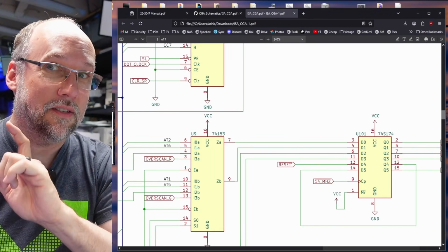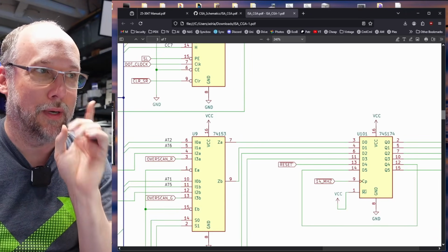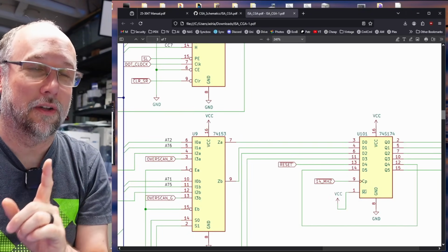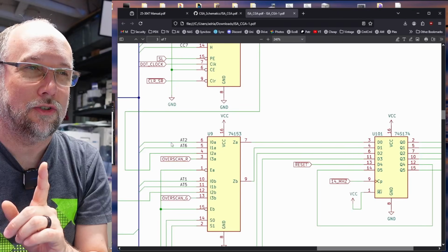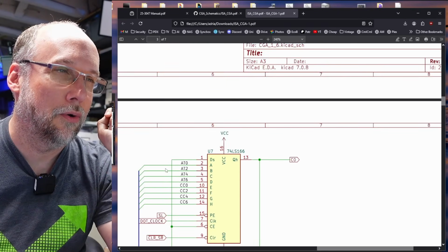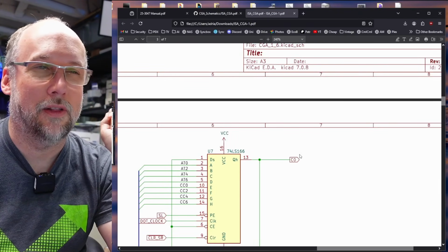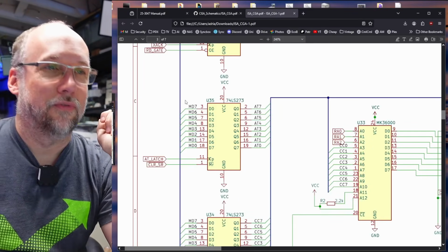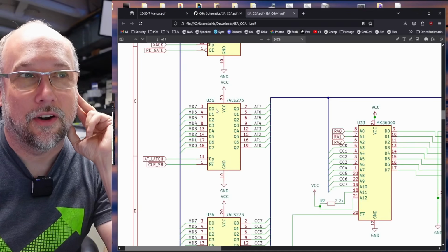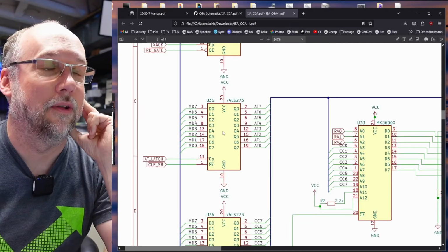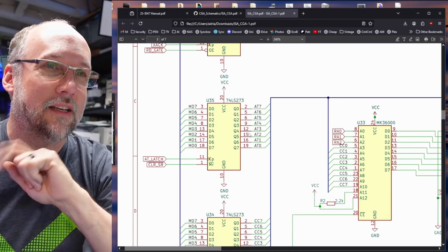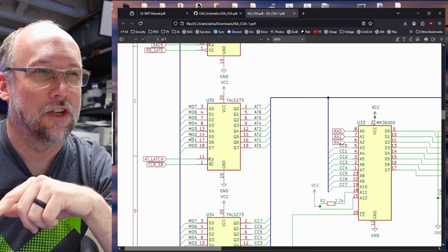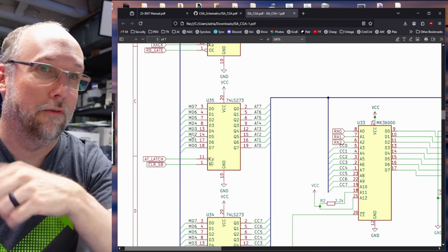And that right there tells us that if we were dealing with this exact problem on a real IBM CGA card, with this AT2 line missing and also this AT2 line up here that would create that missing pixel on the C0 here, then we know for sure that it would be this particular IC right here that's the problem. This pin 15 will be stuck at 0 all the time. And that's hooked up to data line 2 on the RAM chips.